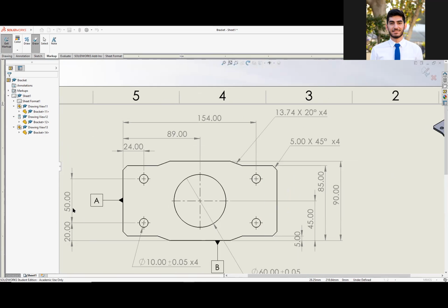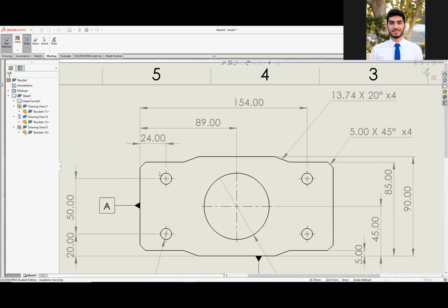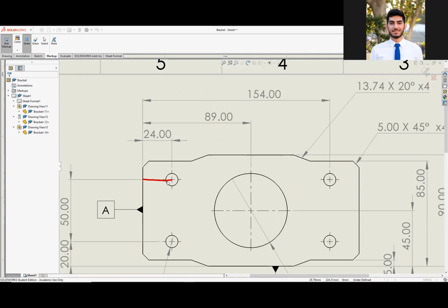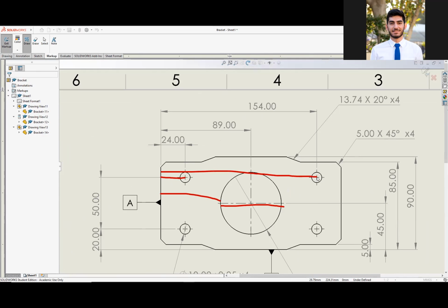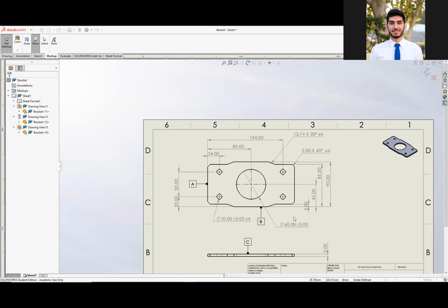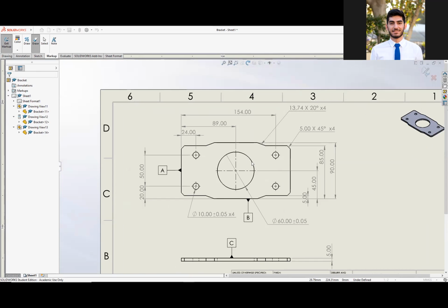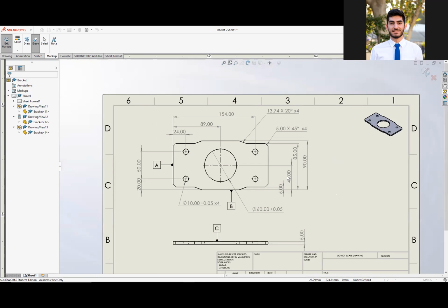That won't happen because you have everything fully defined. You want me to measure from here to here with the caliper, measure the radius of the hole, measure from here to here with the caliper. It's all completely laid out in a way where I know exactly what you're asking of me as the manufacturer, and as the engineer if I give you the part back after I've made it.